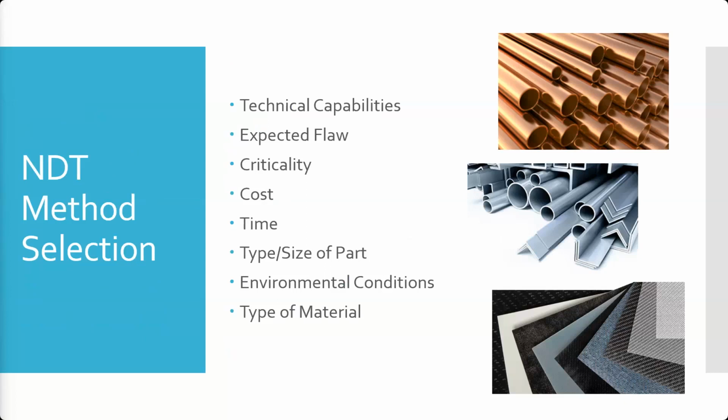Environmental conditions. A day like today would be very hard to do thermographic inspection of an aircraft. Because everywhere you get a piece of snow on the airplane that melts into water, you're going to get a false indication from a cold spot. It'd be really hard to find a delamination. You use thermography to find things like delamination and water ingress in composite materials. Well, water on the surface looks a lot like water that's on the inside too. It's kind of hard to tell them apart. So if you've got a bunch of snow and water on an airplane, you probably can't use thermographic inspection outdoors today.